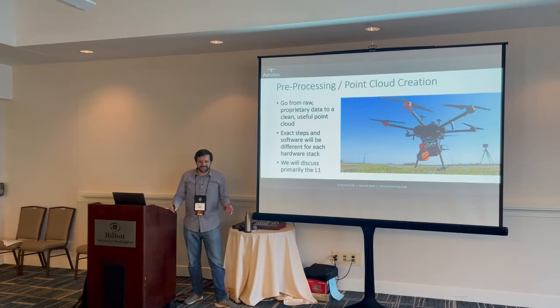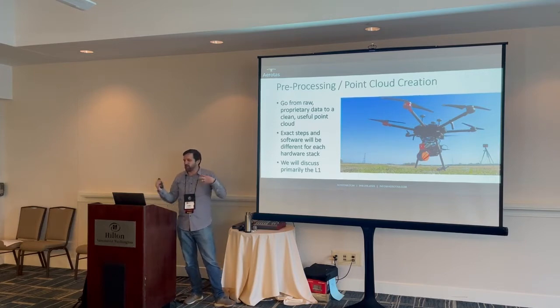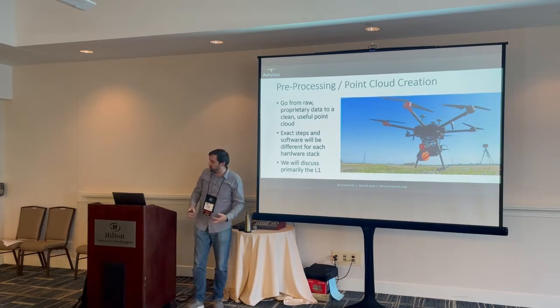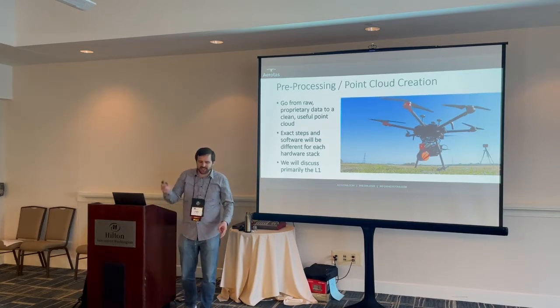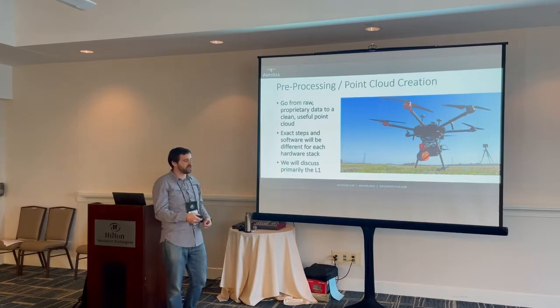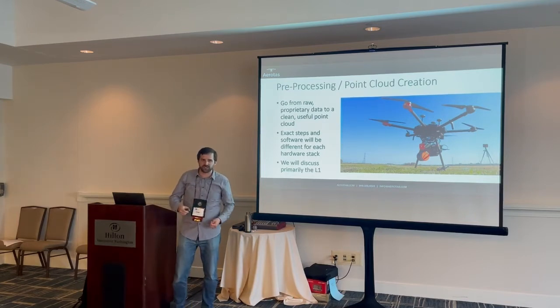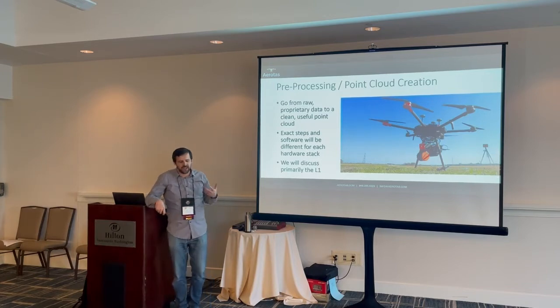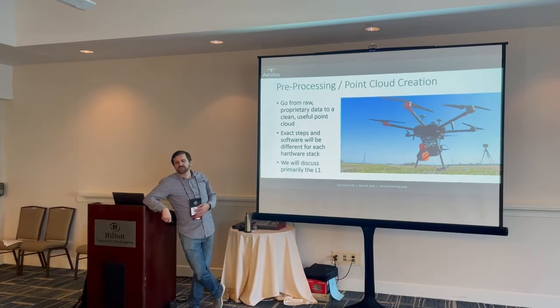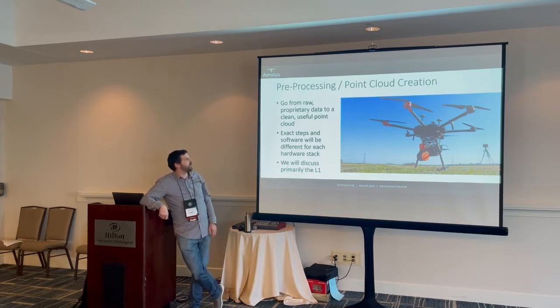What this does, and I mentioned this earlier, is take you from raw proprietary data to a clean, useful point cloud format. Your point cloud format is typically going to be LAS, for laser scanner file, or LAZ, which is a zipped format, but there are dozens of different formats point clouds can be saved in. LAS and LAZ are just the most common. There are also XYZ or text files, and a whole bunch more.